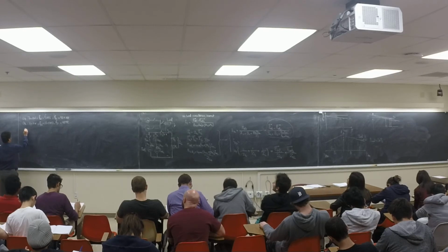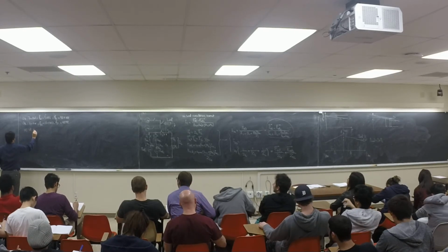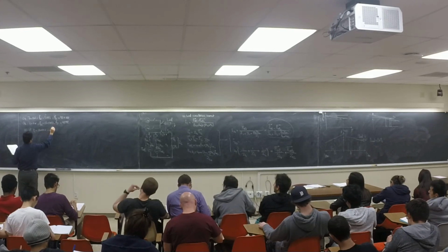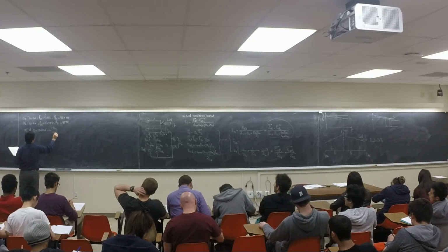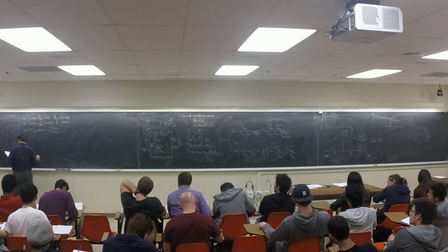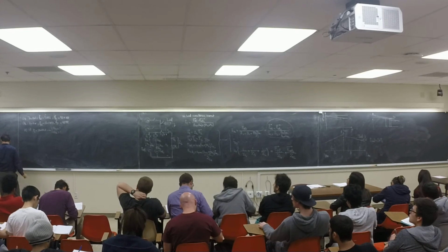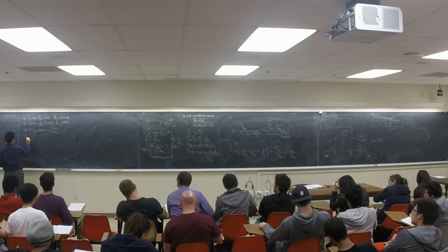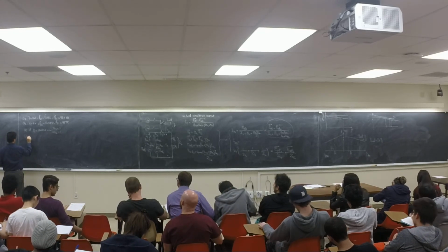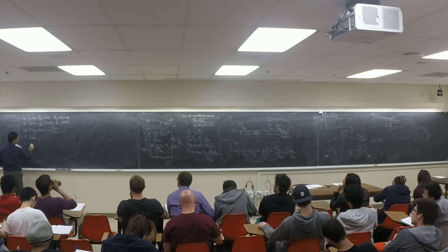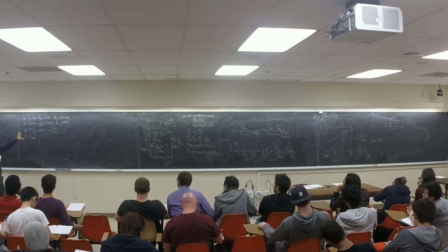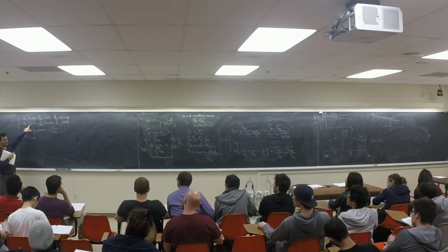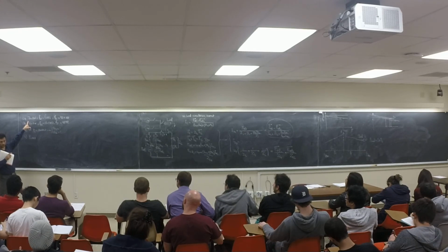First we want to know if PL is 1200 kilowatt, how much is the P G1 and P G2? How are they going to share the load? B, what is the PL max? Let me say it this way. What is the PL max? What's the maximum load we can support without overloading the generator?